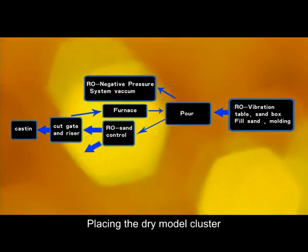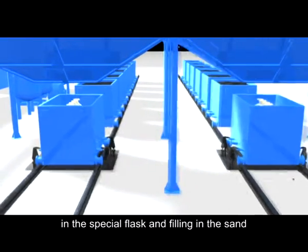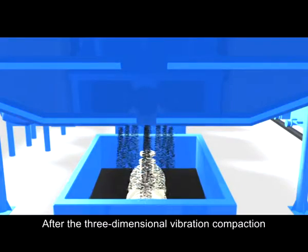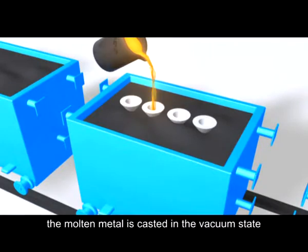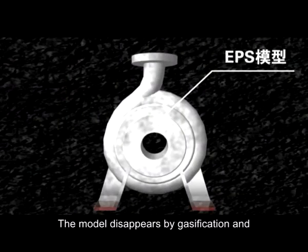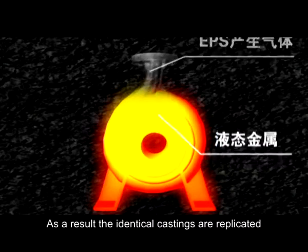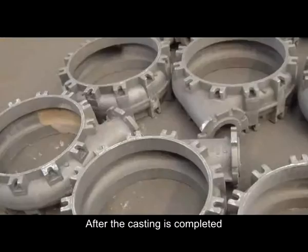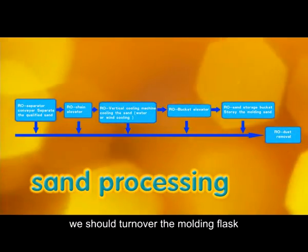We place the dry model cluster in the special flask and fill in the sand according to the process requirements. After the three-dimensional vibration compaction, we cast molten metal in the vacuum state. Meanwhile, the model disappears by gasification and the molten iron takes the place of the model. As a result, identical castings are replicated. After the casting is completed, we need to turn over the molding flask.